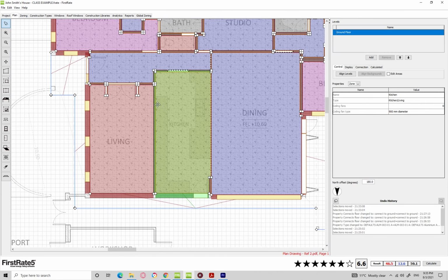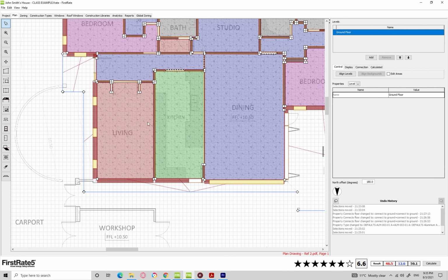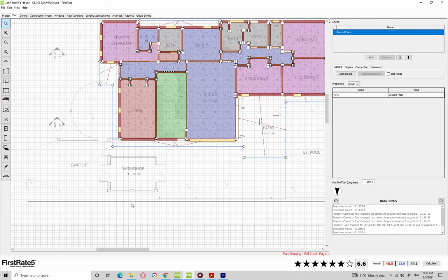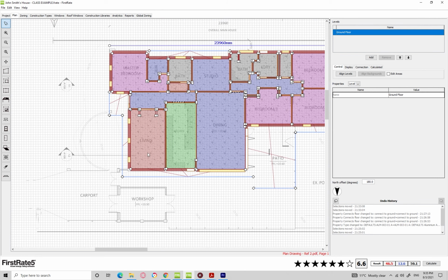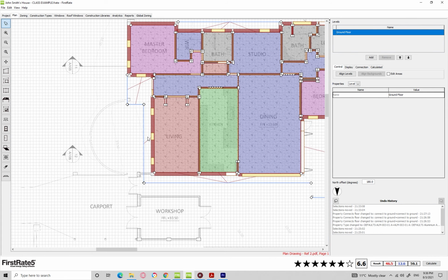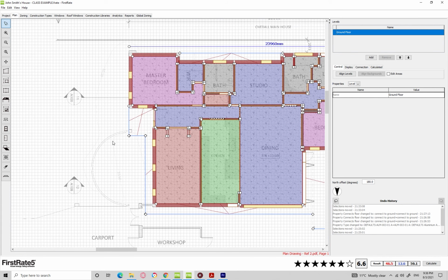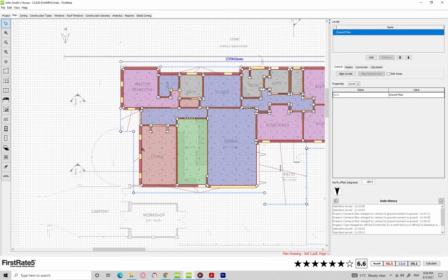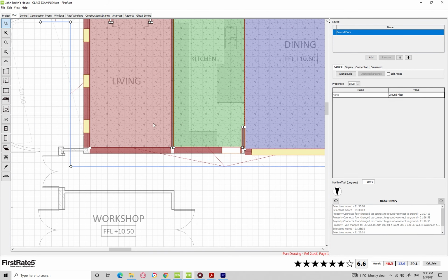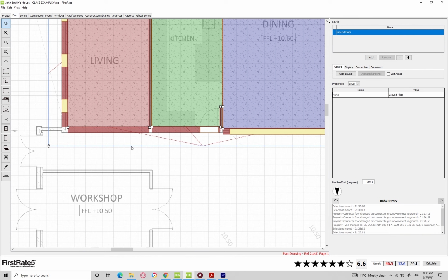And we might start to wonder, why is that the case? Well, if we look at the plan, we can see, for example, the living, as we discussed, has no windows to north, so it's not getting that direct sunlight from the north. It's only getting sunlight here to the east, okay? So during sunrise, there will be sunlight coming in.